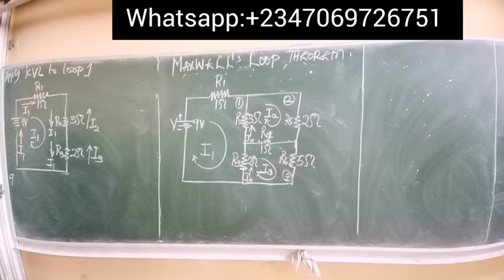This current I1 flows through the first resistor R1. There's always going to be a potential drop whenever a current flows through a resistor. Because of that potential drop, we always attach minus times the potential difference, which is resistor times current. The resistor here is R1, and the value of R1 was given as 1. So you simply have 1 times I1, the current flowing through it.